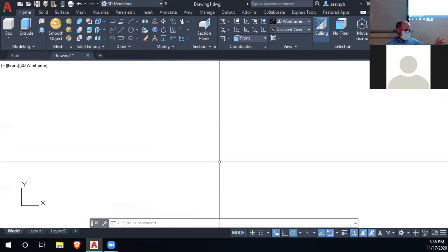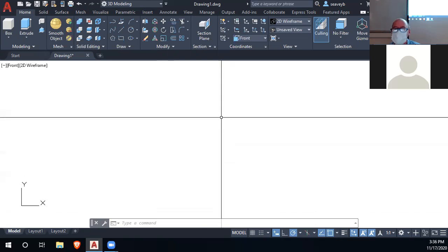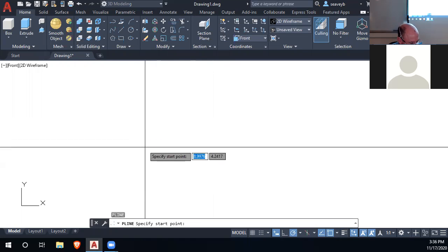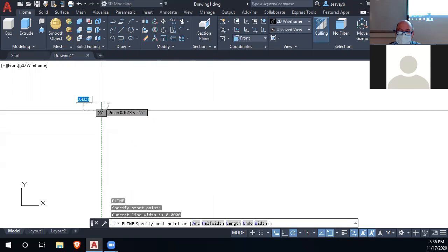Okay. So because we're drawing in 3D, we're actually going to start in 2D, right? So I go to the front view, which is a 2D view, and I'm going to draw that slanted shape, okay? But I also want to draw it using a polyline, not just a regular line, right? So instead of L space bar, I would use PL for polyline. It's actually two kinds of polylines, but this one's just PL space. And I'm going to draw this thing. It looks like it's 2.5 inches tall by 5 inches long.